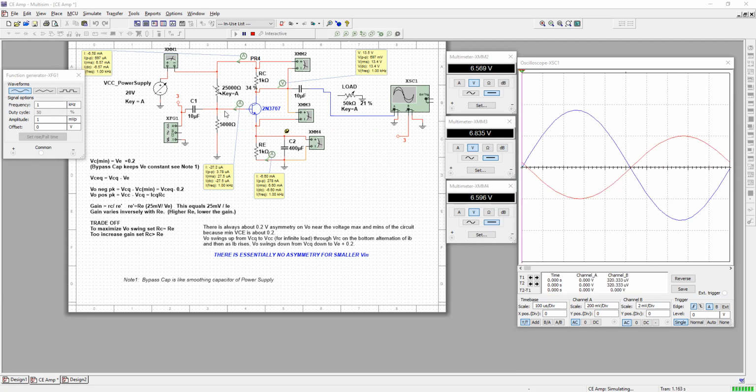All we're saying is that the current that is flowing is supposed to be very small compared to the current that's flowing through the voltage divider. Remember our basic circuits lessons, when we had a voltage divider that was loaded, that load would always bring down the voltage slightly because it was going to create a different mix of resistance.